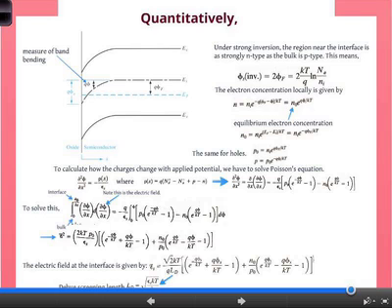And can it bend so much that the conduction band level crosses the Fermi level? Yes, you can. The design is such that it can. It's a good question because it's a lot of band bending, which means you need lots of field. Okay? It's a very good question from a practical perspective. To get a lot of field, it doesn't mean you need a lot of voltage, as we just saw for short channel. You can make the gate oxide really, really thin.